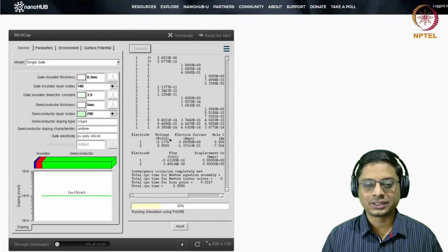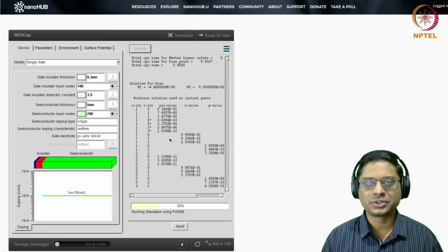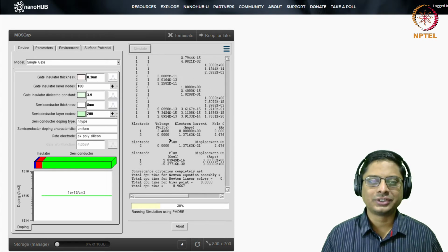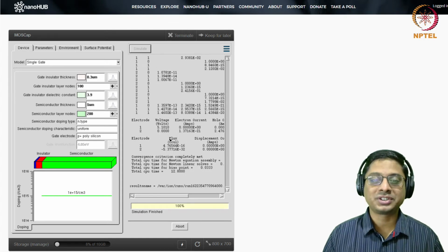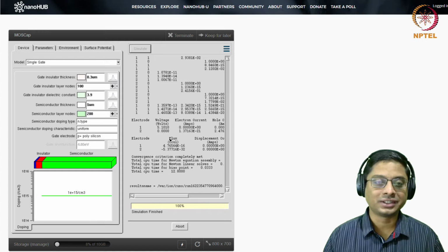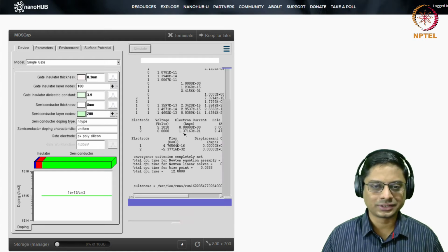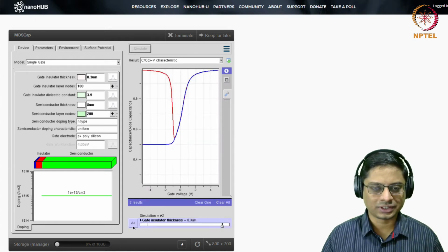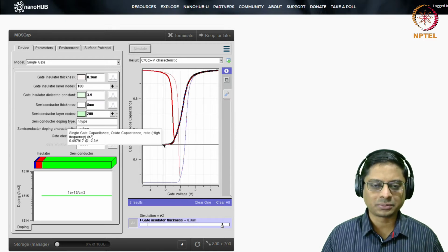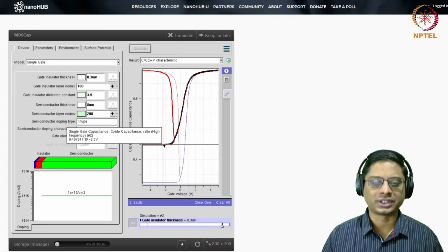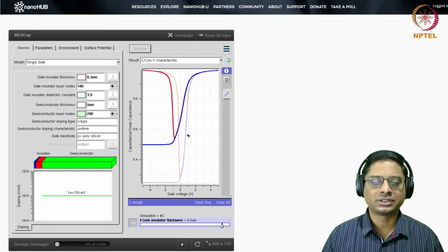But that is the normalized capacitance that I showed in the lecture. Because the oxide capacitance also should change, obviously, since we are changing the thickness of the oxide. We didn't show you that. So let's do that. This is the original simulation with 0.1 micron thick oxide, and then the second simulation with 0.3 micron thick oxide. And of course, we saw why the VT shift was happening. We explained this in the class.